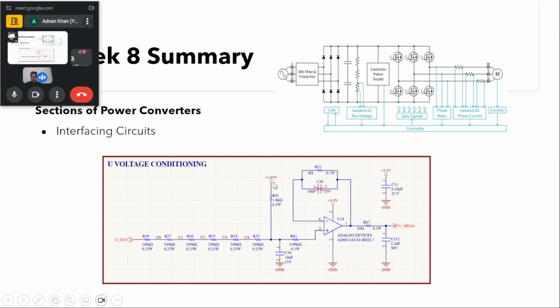Here, if you can see, an offset of 1.65 volts is provided, because now our 0 will correspond to this offset voltage, and a voltage above this offset voltage will correspond to the positive voltage, and the voltage below this offset voltage will correspond to the negative voltage. And after that, we give that voltage to the microcontrollers.